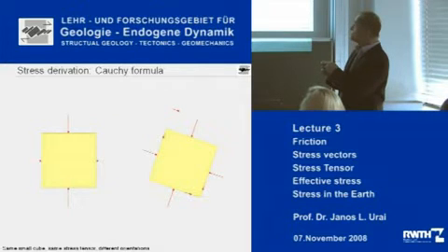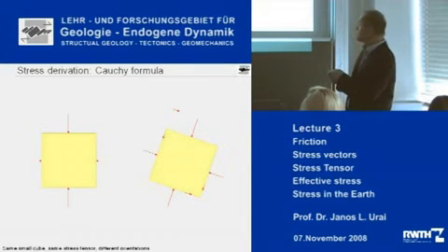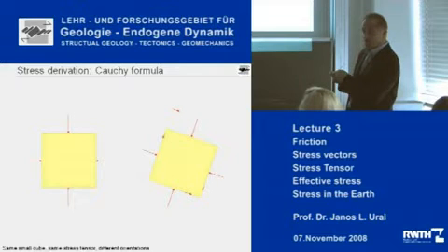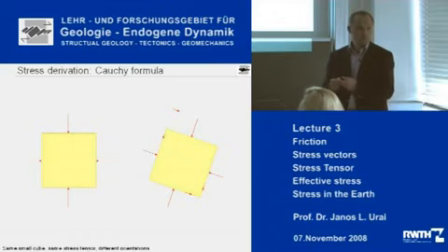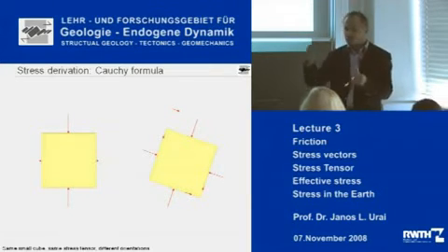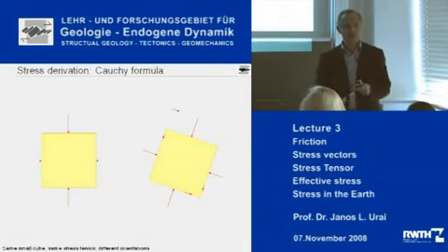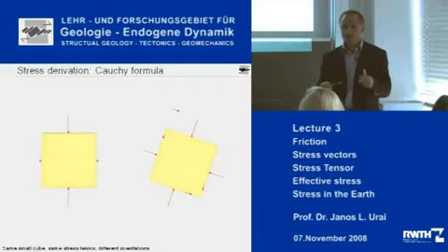We have learned that to get equilibrium, this one and that one have to be the same, otherwise my little cube starts to spin. And if you now take the normal and the shear component of that stress tensor for all the different planes possible, and you plot them, you get a circle. So this stress in a point, which is really the collection of stress vectors on all different possible planes, can be represented by this Mohr circle diagram. In future lectures, I really expect you to understand this in some basic way, because I'm going to draw a lot of Mohr circles during this course.